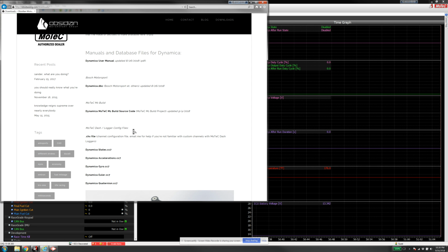But I'm trying to make it so that you don't need to do anything other than plug the sensor into a harness and use a DBC file, or an M1 build's example project, or these CHX files, which use MoTeC's channel editor software.